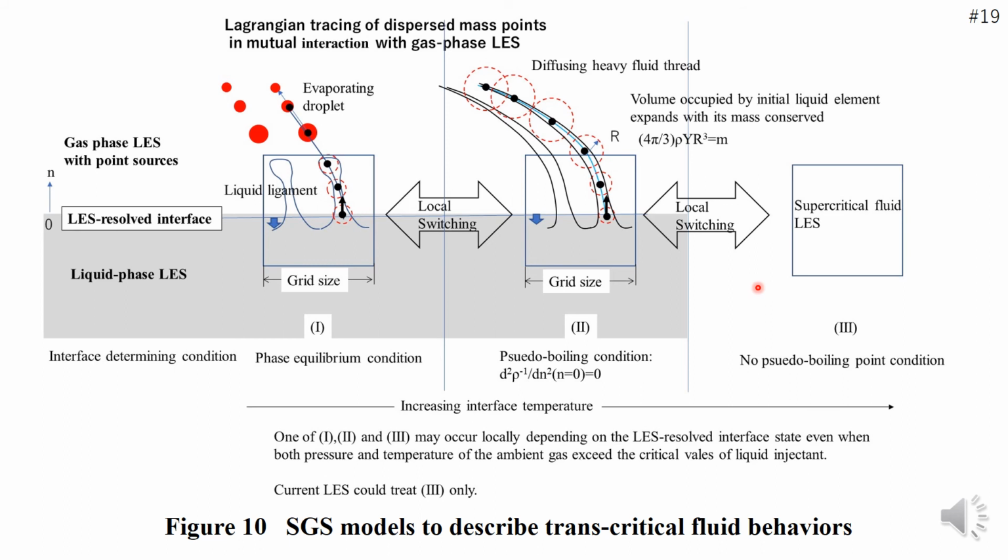This slide illustrates how the proposed two-phase flow LES could cover all transcritical mixing processes. Again, the shape and thermodynamic state of the local pseudo-interface change temporospatially because the dense fluid spike formation changes the subsequent light fluid LES flow field evolution, and the pseudo-interface behavior itself as well.